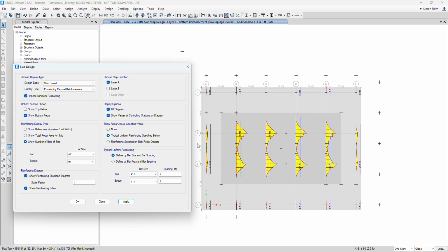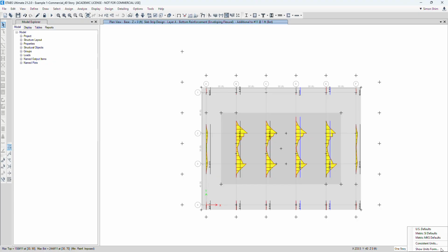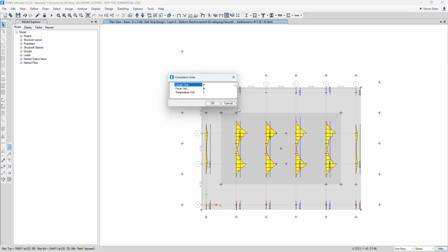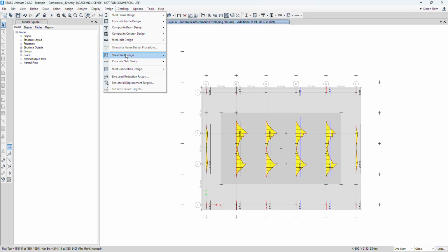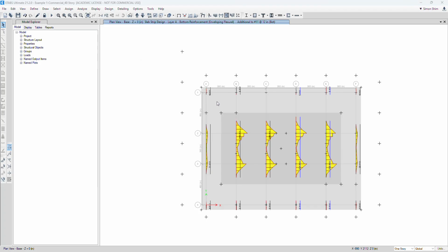But overall, remind yourself it is a spread footing design procedure, and this is almost identical. This is only a finite element software, right? So if you follow along, I think you may get there. Now, this is some additional. During the design phases, this is output. We need to really iterate to find out what bar and spacing we need. So change to inches and output again.